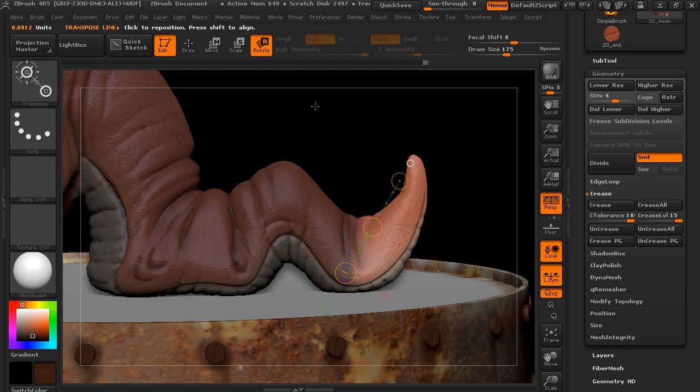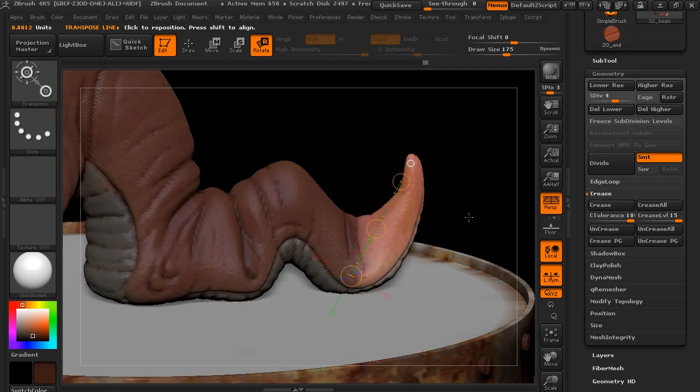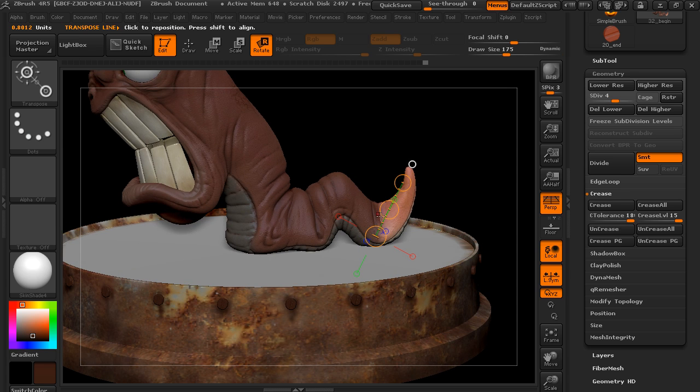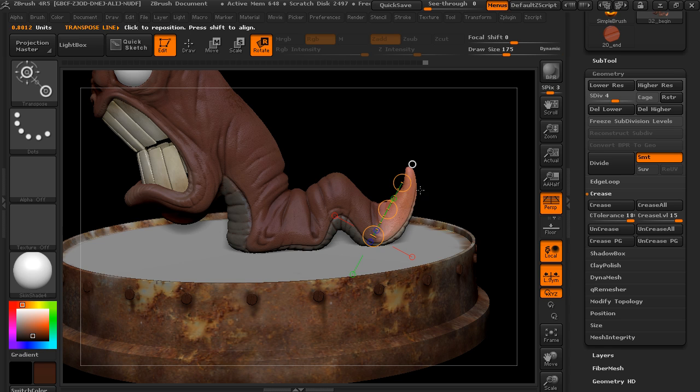Okay, rotation will help keep its size and the shape that we want it to have. So if you have an arm or something, control drag down the arm to create that topological mask, and then create your transpose line. It's sort of a temporary joint to pose it. Then you could move down and pose the elbow and so forth.